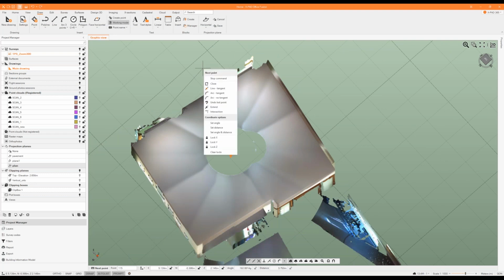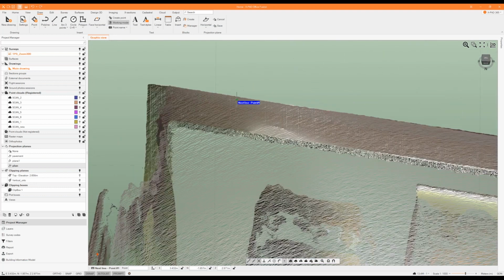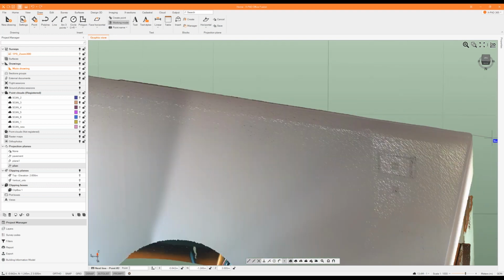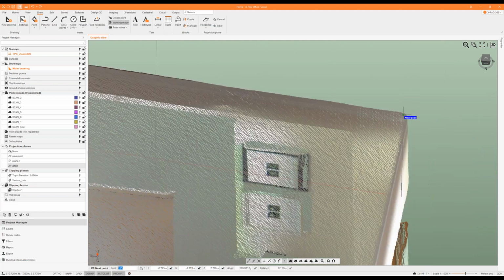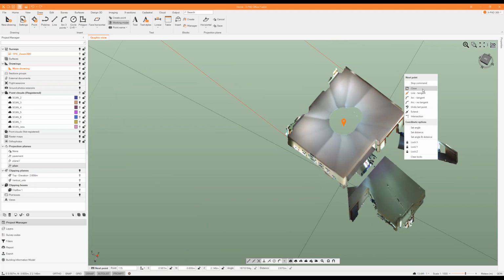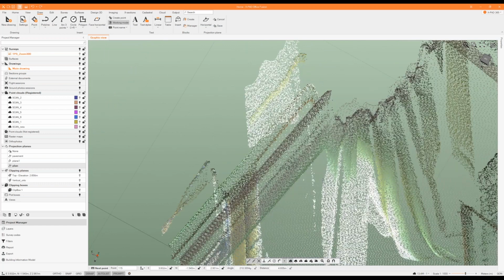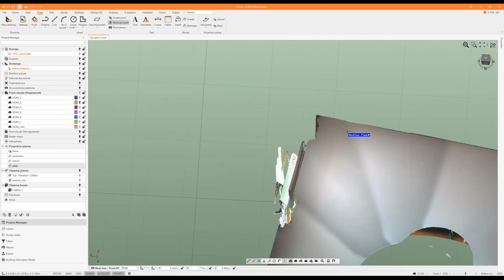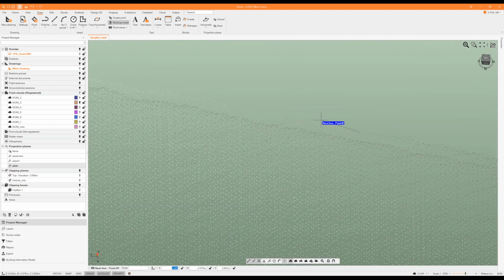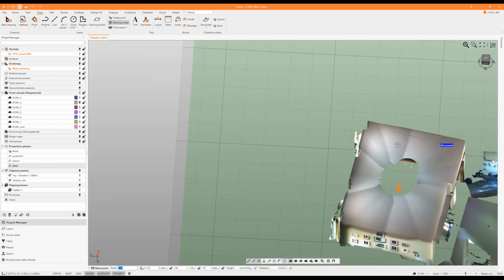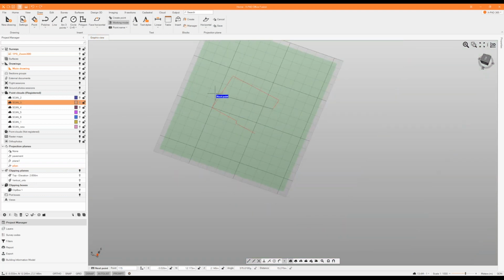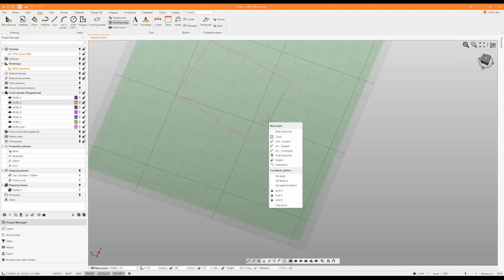for example, right click with the mouse, intersection. So in that case, we measured only the point here in this angle. Then we can select 2 points in the other plane, and automatically the software, sorry, undo last point. Okay, I will select another point here, intersection. And here we are. Then I can simply hide the point clouds. So we measure 2 points in this plane, then we select 2 points in the other plane to create also the projection in the angle. Then right click, close.